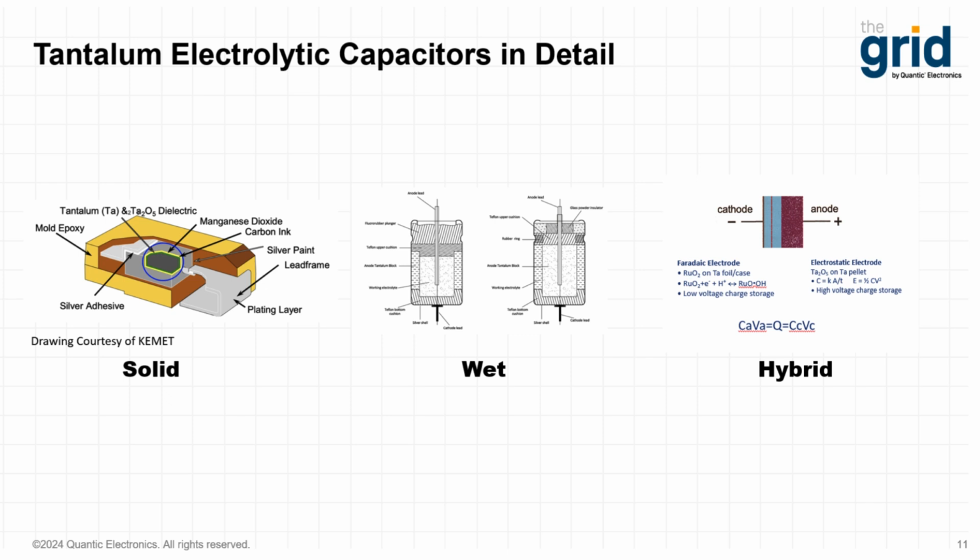The dielectric is then surrounded by an electrolyte, which can be liquid or solid, again, similar to that of its aluminum counterpart. The capacitor case and electrolyte together serve as a cathode in tantalum capacitors. Wet tantalum capacitors are self-healing, making them electrically robust. These wet styles are known for their high energy density compared to solid tantalums and aluminum electrolytics.